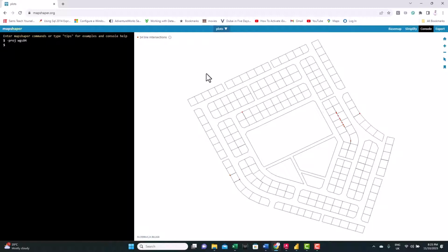Now, if you remember, we exported the area and we assigned an ID for each of the plots. Also, you can see them from here. So if you go to the select option here, you can select inspect features. If you click on it and hover over any of the plots, you can see on the top left corner the area and the ID showing. So that's it. We're ready now to export this map to a TopoJSON file, and also we'll export a CSV file. Let me show you how to do this.